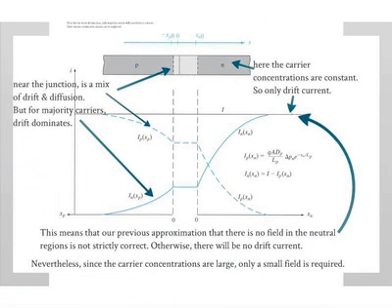So first of all, the thing we know is that we know the diode equation, right? So for an applied voltage, we know that the current is given by I naught times e raised to qV over kT minus 1. Right? This we know. This is the total current. So this is made up of some hole current and some electron current. The question is to find this.